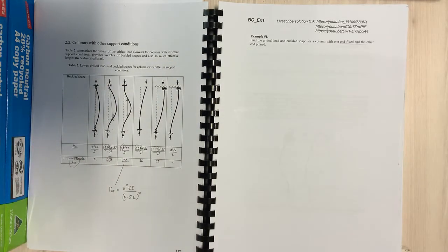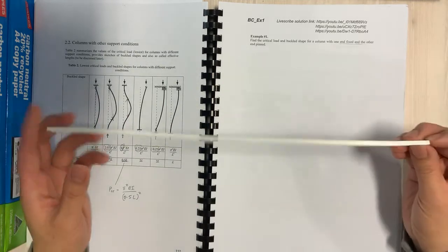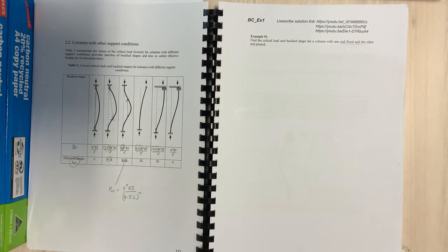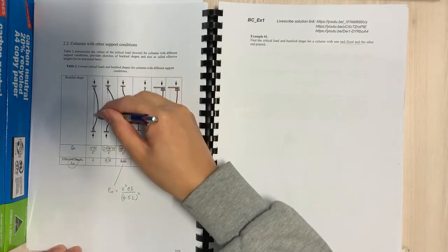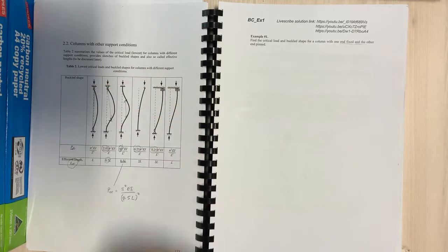So the sudden buckle occurs at this Euler load, which is pi squared EI over L squared, and that's also known as the elastic critical load. And a beam, a column, or a beam column can't take any more load than the theoretical Euler load, pi squared EI over L squared. So that was for that case there, which you can see.